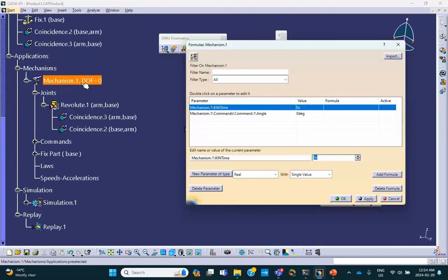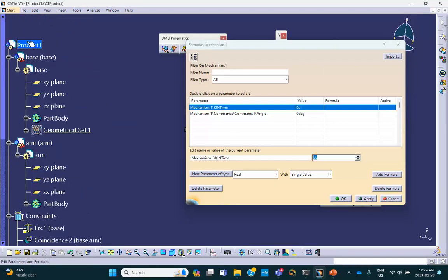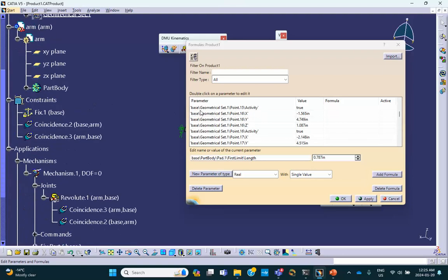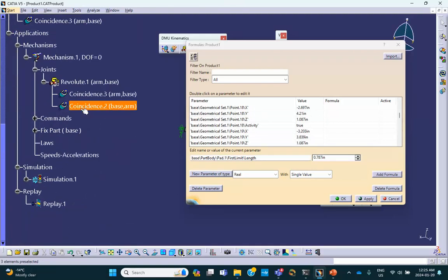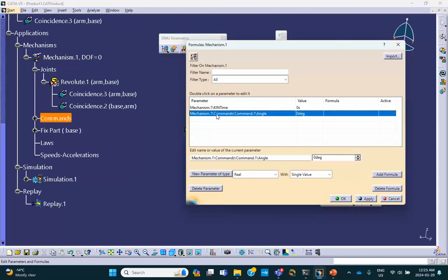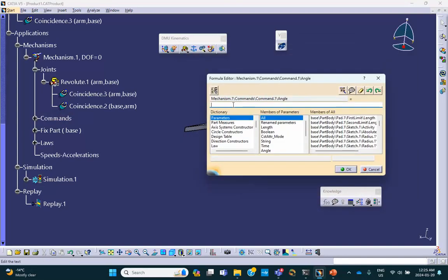This is the database for the entire product. Everything that you have in here is reflected in this database. But if you're interested only in mechanism, you click on the mechanism, and there are really two things, time and the command. So if you select the command and add a formula, it says the angle equal to...